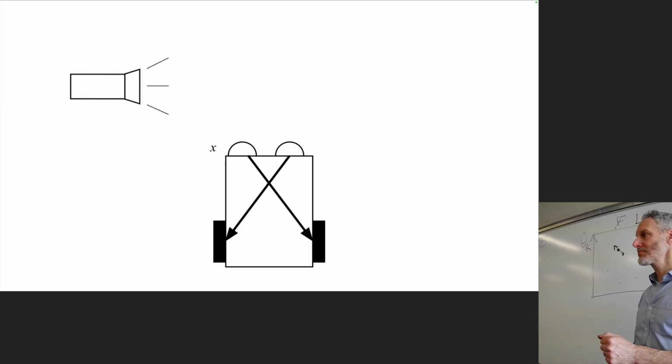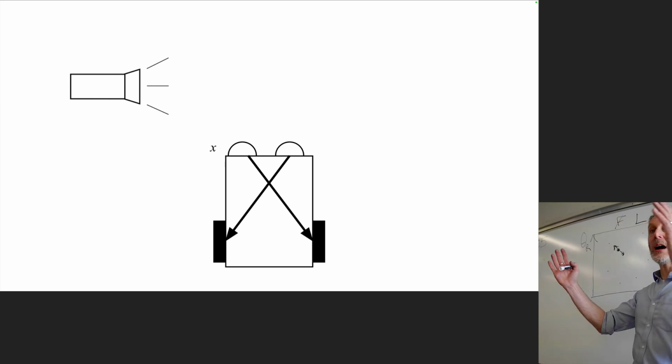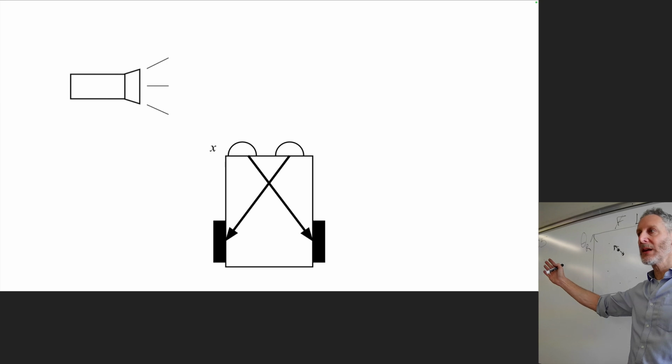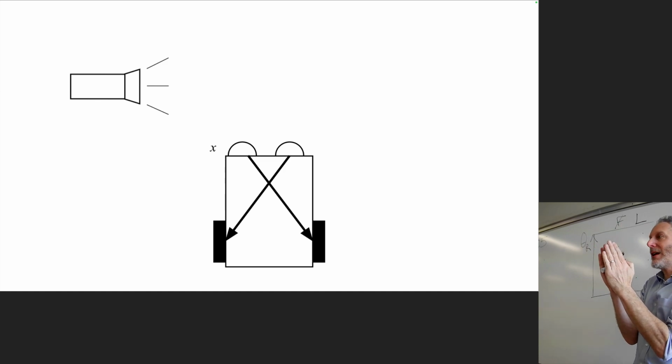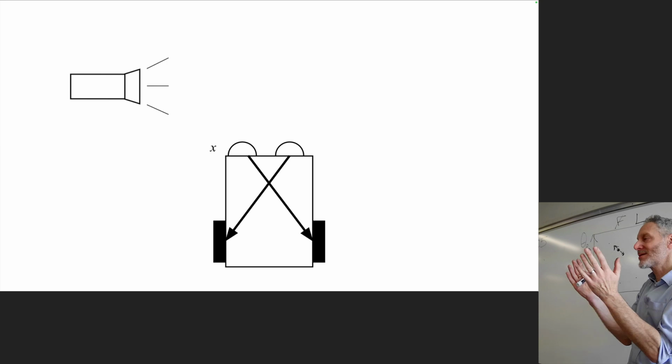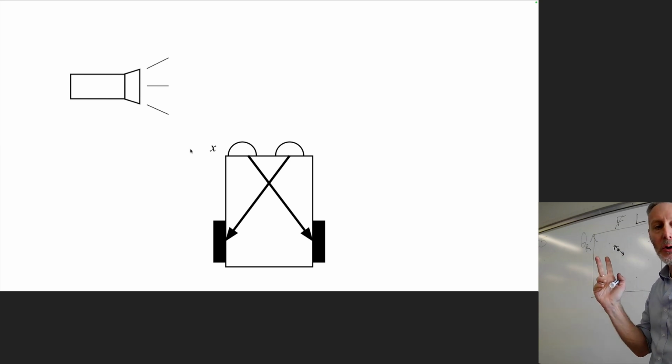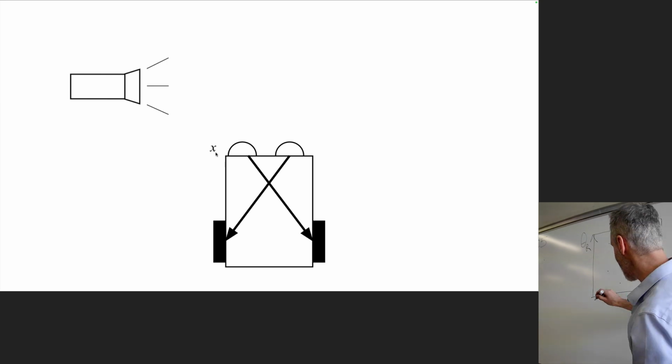Other ideas? Well, it just has a wider range of distance that it can see the light from. Yes, absolutely. Maybe it can just see further. The difference between these two light sensor values is also greater, right? If you have these two light sensors right up next to one another or sitting right on top of one another, the robot can't tell left from right. So we could think about trying to optimize or find a good value for x as well.